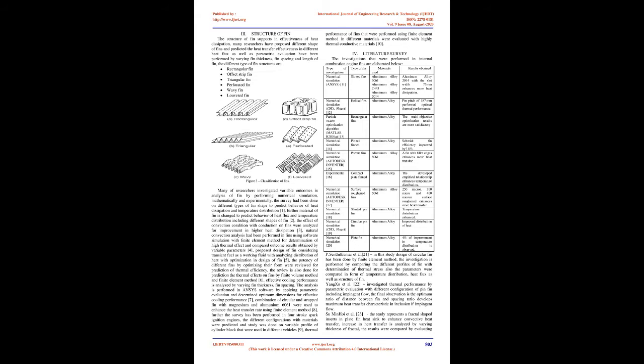Rectangular fins and triangular fins are straight fins. Triangular fins are attractive, since for an equivalent heat transfer they need much lower volume than rectangular fins. Hence the fins have practical importance because they give maximum heat flow per unit mass with easy manufacture.